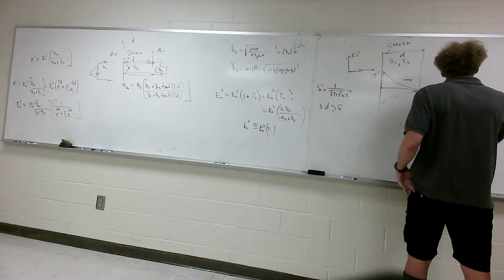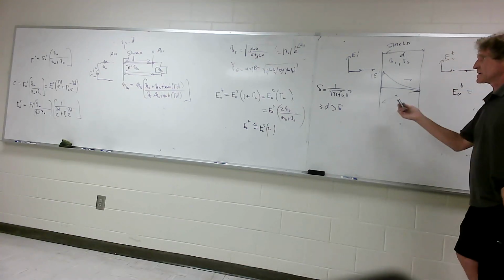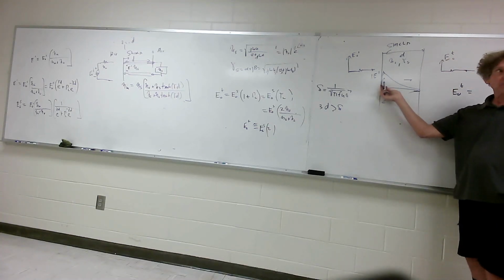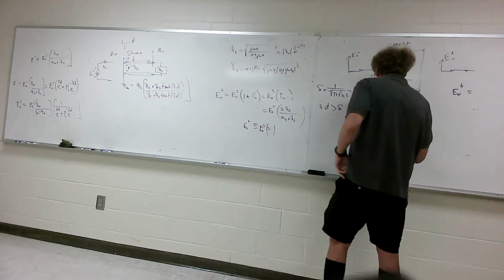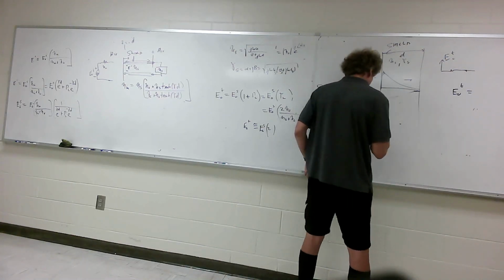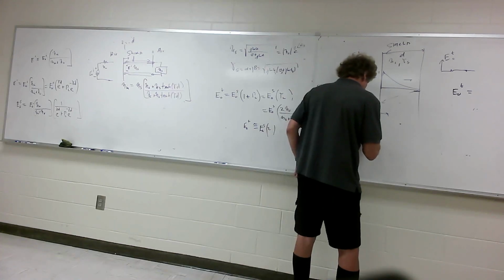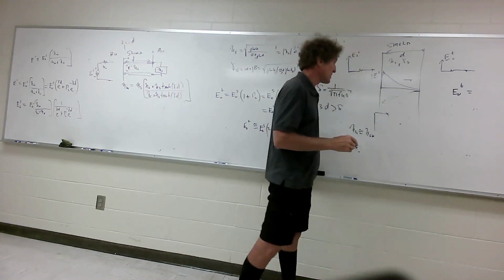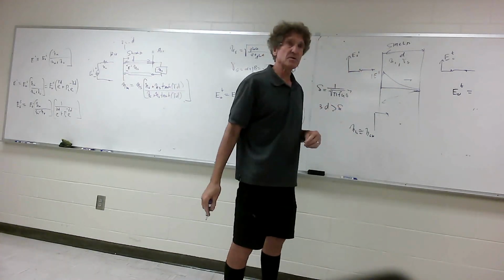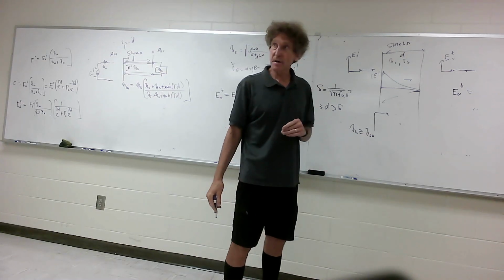If this is the case, and it's just an approximation, then you can say that the electric field transmitted... Now follow me. Got an incident field here, right? I'm going to do a couple things. I can say that my eta in here is just approximately eta shield. You don't need to worry about the transmission line formula for that. Does that make sense to everybody, class?